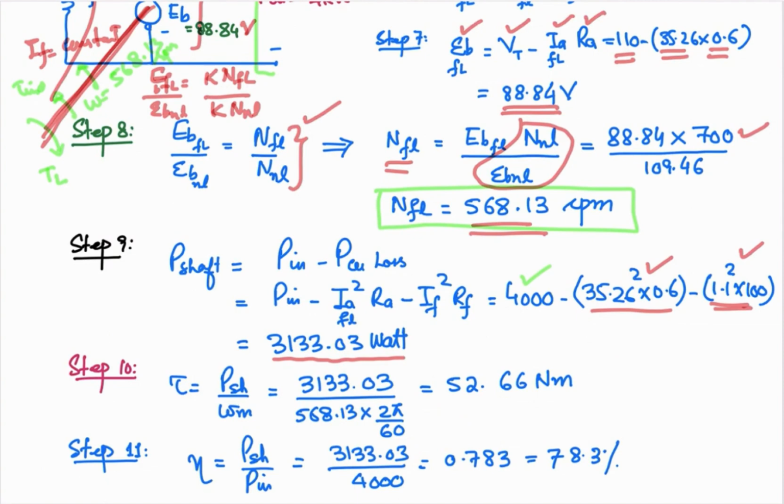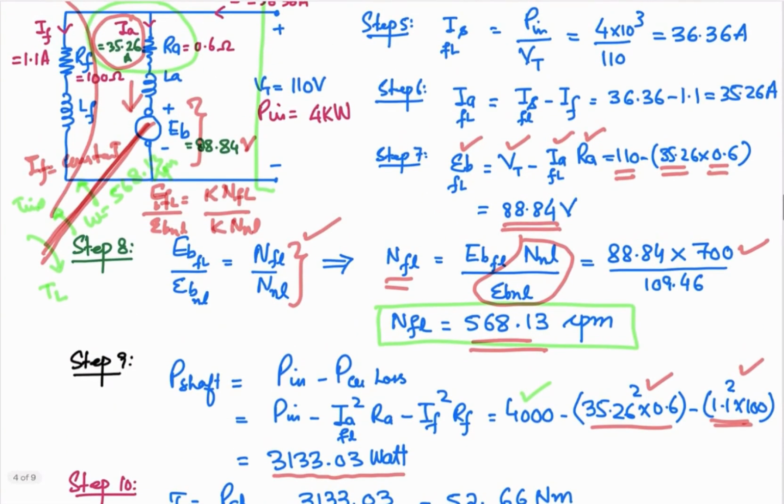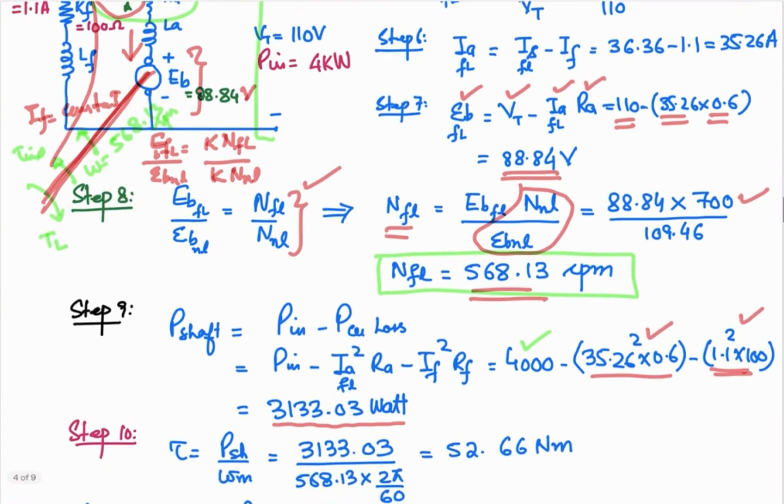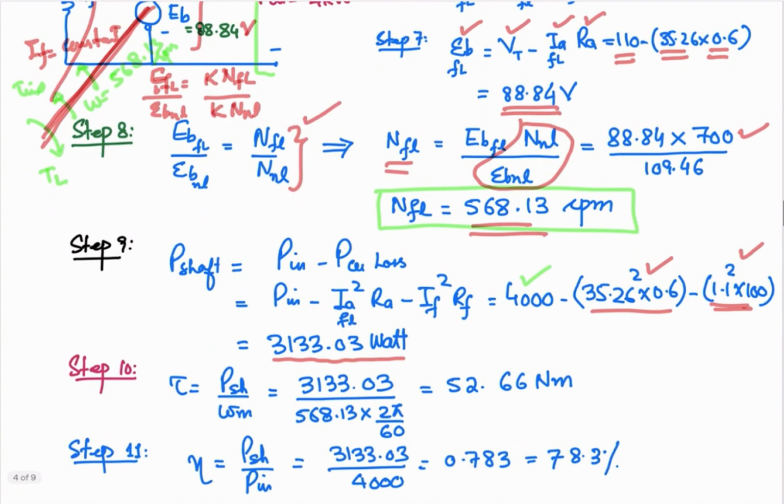This is the torque that will be developed at the shaft because of the power that is converted from the electrical to the mechanical form. So that is the torque induced, and we are going to consider it as the T shaft at the moment because there is no loss. If there were frictional loss or windage loss, you would have to account for the loss in the torque because of those frictions, and then the rest of the torque will be available to the load. So if that information is given, you can work out the load torque.